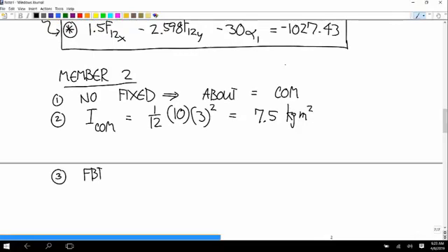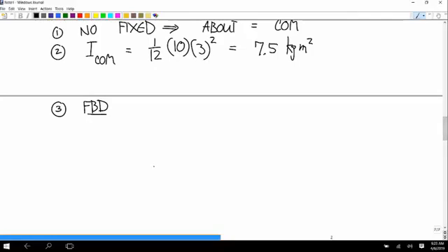And then the free body diagram. There's a weight force of 98.1. Up at the joint B where the two bodies connect, there's a pin joint. And so we have the force on 2 by 1, which is negative F12. What about the 600 Newton force? That's not there because we associated the pin with member 1. So that only comes through to this member in the reaction force.